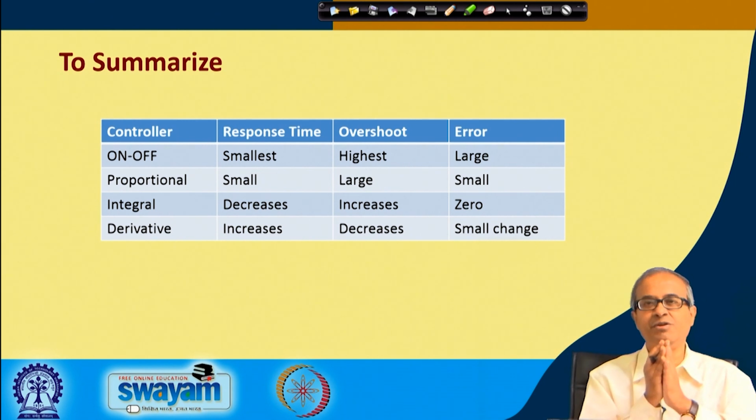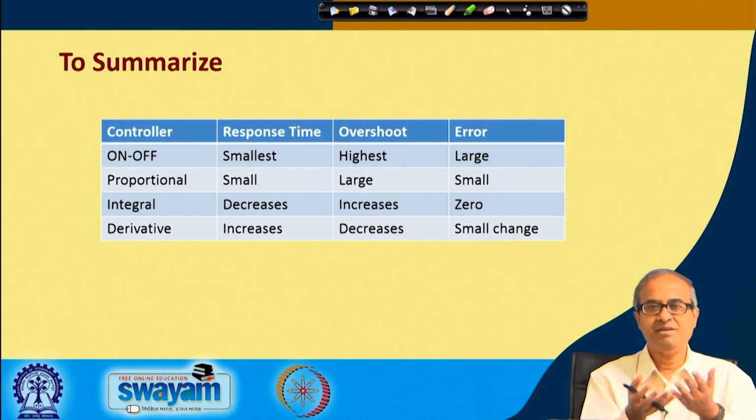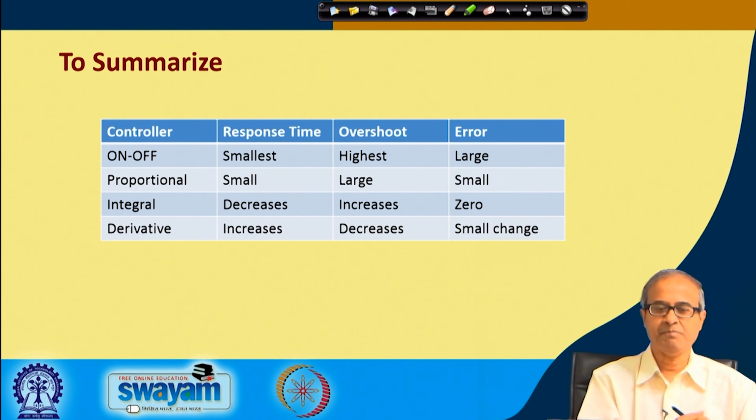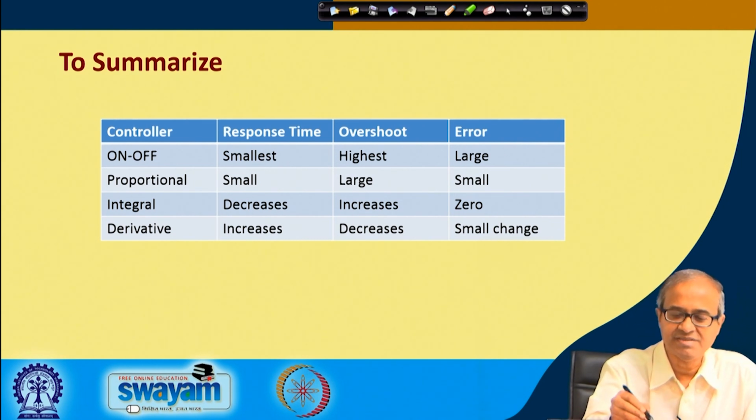But all these things are really not required, you need to understand better about the parameter you are trying to control in an application, and then you can select an appropriate method of control. Now, in the experiments that we shall be showing, for simplicity mostly we shall be using on off kind of control, because it is easier to show you, demonstrate, and also easier to write the program. Because you see, whether you use on off or PID control depends entirely on your software, nothing to do with the hardware. The hardware remains the same.